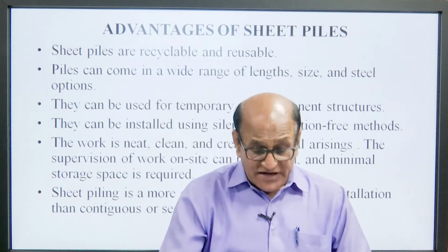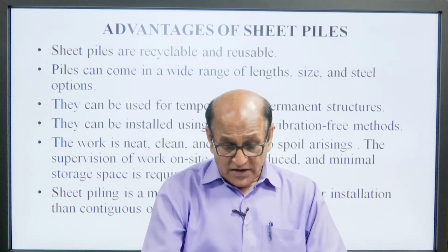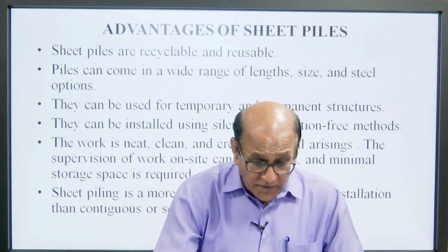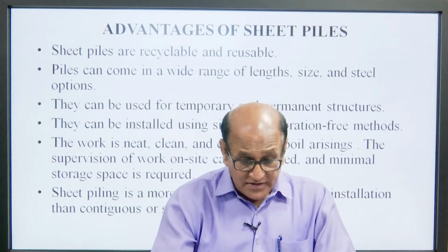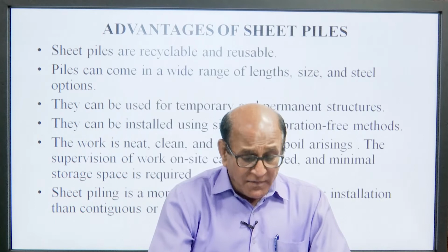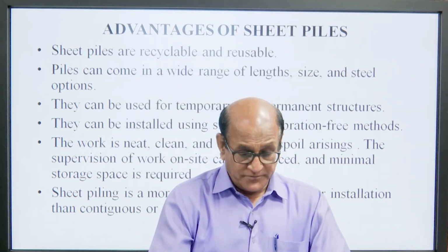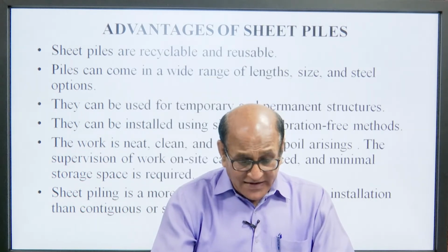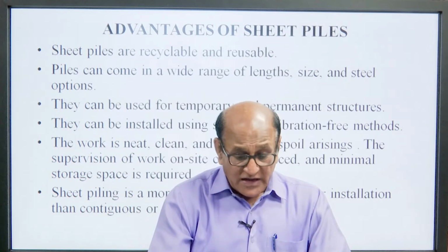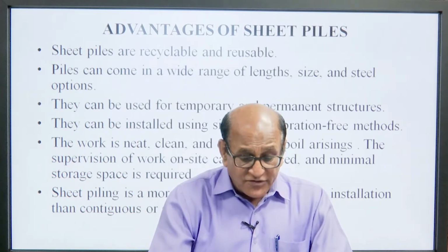The work is neat and clean and creates no spoil arisings. The supervision of work on site can be reduced and minimal storage space is required. Sheet piling is more cost effective and quicker to install than a continuous concrete wall.